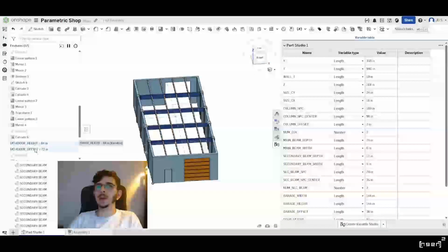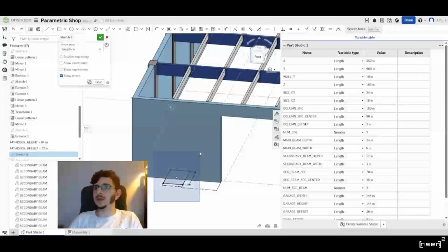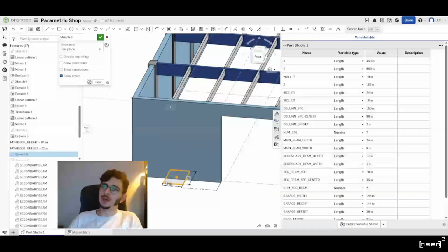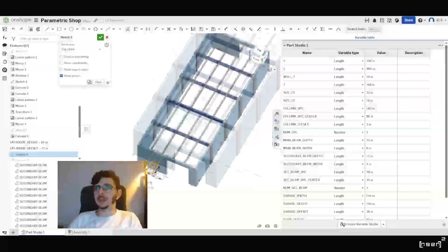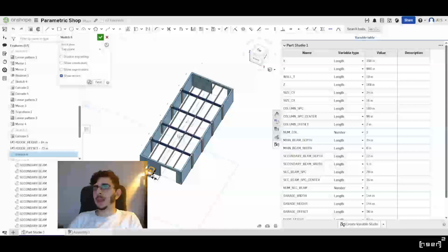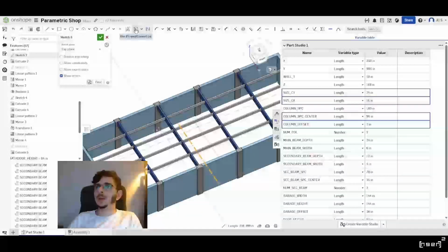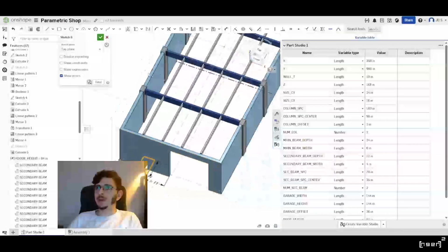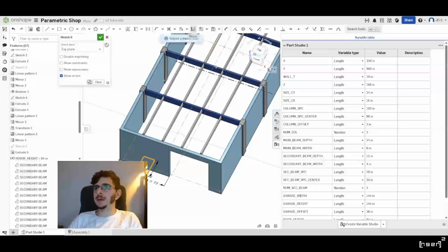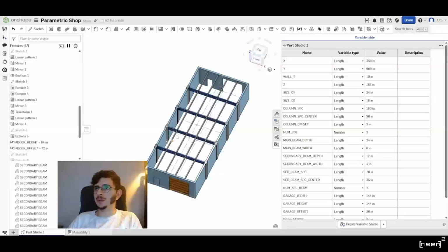Yep, and that's what happens when you link to the sketch instead of linking to some specific lines or areas in a sketch. That's one of the kind of hidden secrets for parametric modeling in Onshape, knowing when to reference a sketch and when to reference part of a sketch, depending on what you want to do.